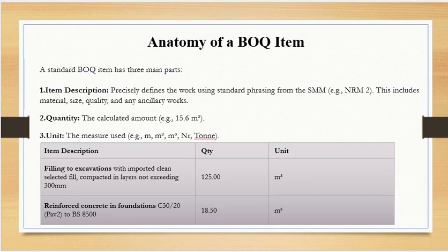Now you can see here excavation. Now they are saying do excavation. Then filling of the excavation, sorry, backfilling. This is item backfilling. Now they are saying the backfilling should be done with clean backfill. So there should not be weak soil in it, there should not be plants in it, there should not be dead people in it, and so on. You get the idea? It should be done in layers. So if I have to fill 1 meter, I will not fill 1 meter in one go, but in layers. And each layer is normally 300 millimeters. This is standard. 300, 200 millimeters standard.